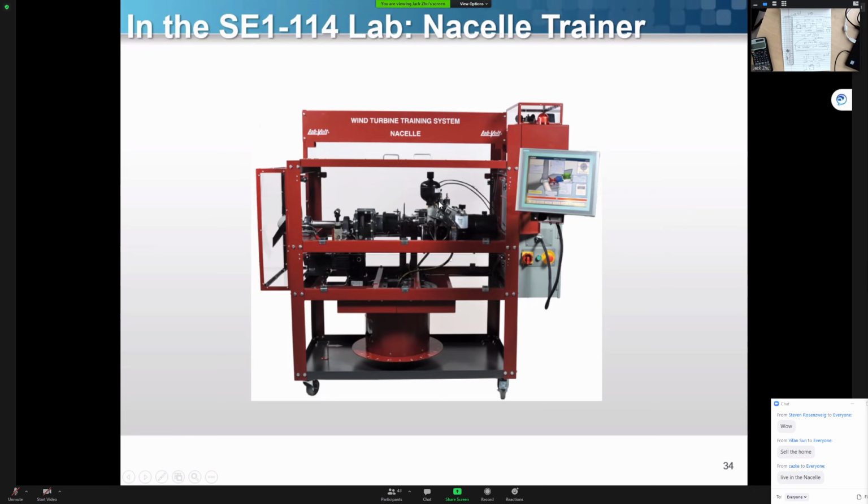They have a lot of hydraulic components inside also, because all those brakes are activated or controlled by the hydraulic system. The electrical system sends the signal, the hydraulic pump runs, and there are solenoid valves to control whether you want to apply the brake or release the brake.